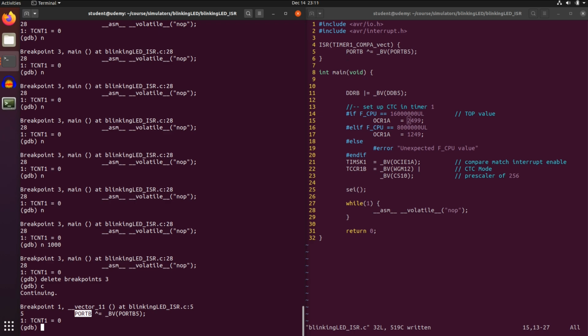The problem with simulators is that they can simulate the behavior of the MCU. But what if the behavior is triggered by some changes in the physical world, or the MCU is supposed to change something, such as the state of the LED that we have in this example? We can print the registers, but how will we make sure that the LED will indeed glow without seeing it? Therefore, simavr can be extended to simulate also the environment. Let me show an example.